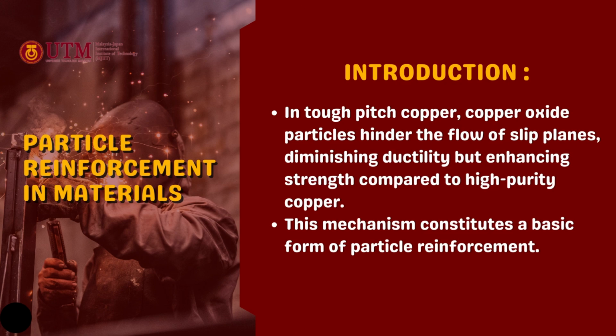Particle reinforcement in materials. Introduction. In tough pitch copper, copper oxide particles hinder the flow of slip planes, diminishing ductility but enhancing strength compared to high purity copper. This mechanism constitutes a basic form of particle reinforcement.